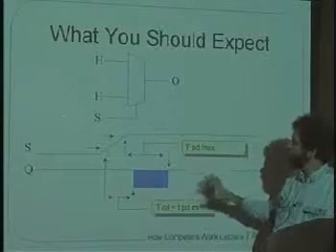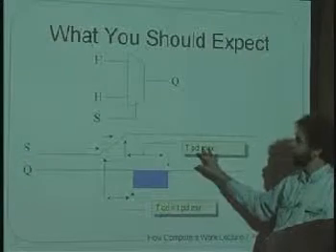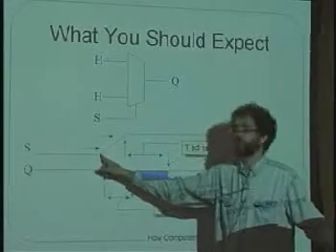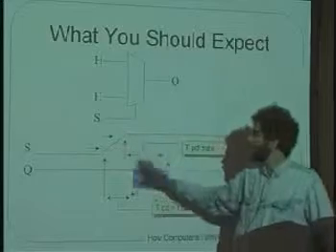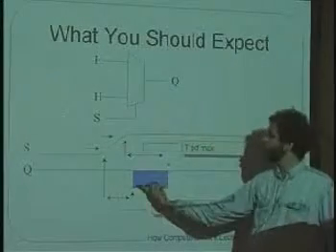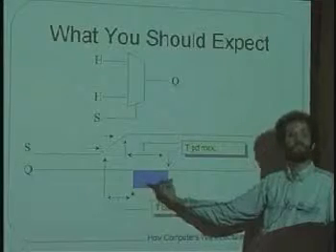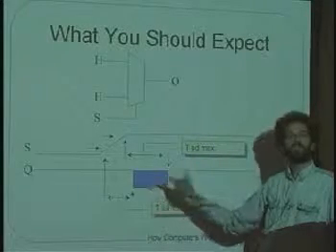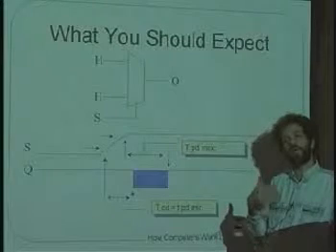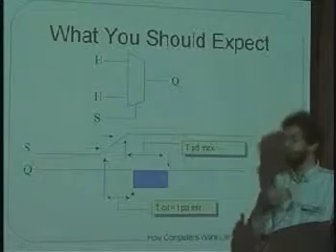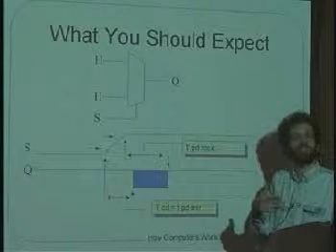So in general, first of all, TCD is usually less than TPD, and furthermore, there's also the time it takes for S to go between being a 0 and a 1. You add those times together and you end up with this time of indeterminacy in the usual specifications of a logic device. Remember, no logic device can figure out anything instantaneously, and what you learned last time and practiced a little bit in recitation is that it's even worse than that.